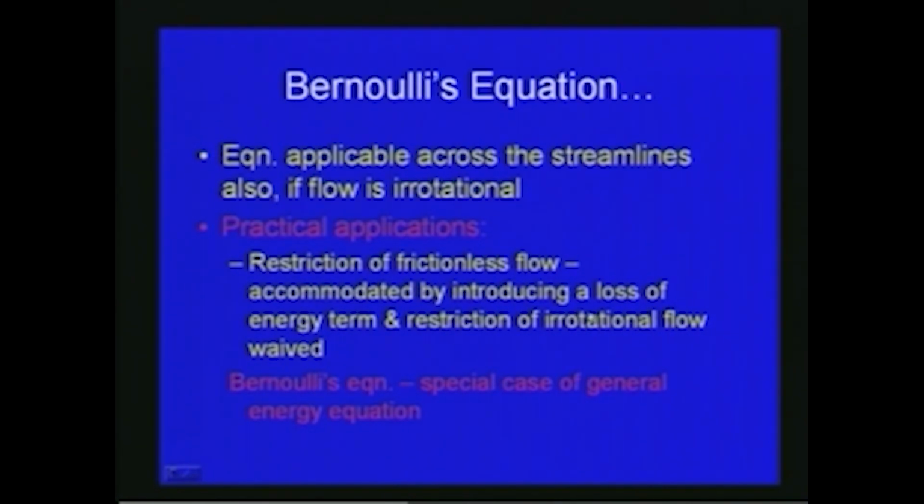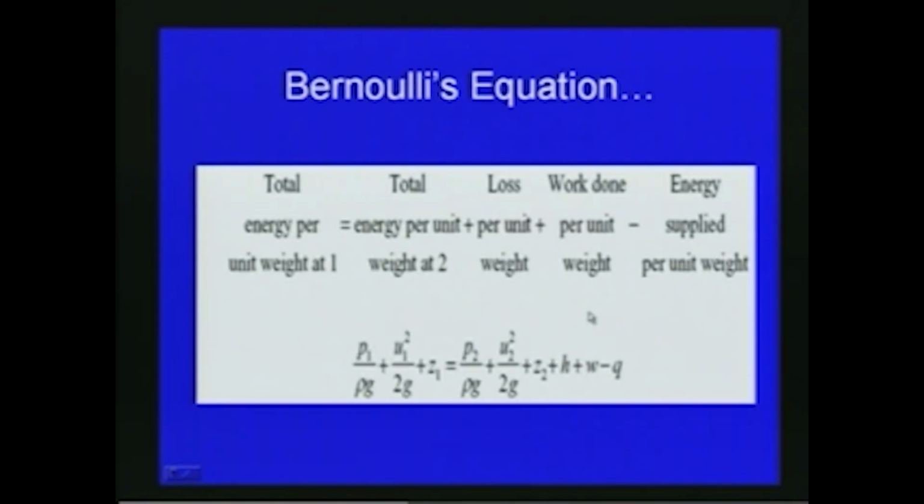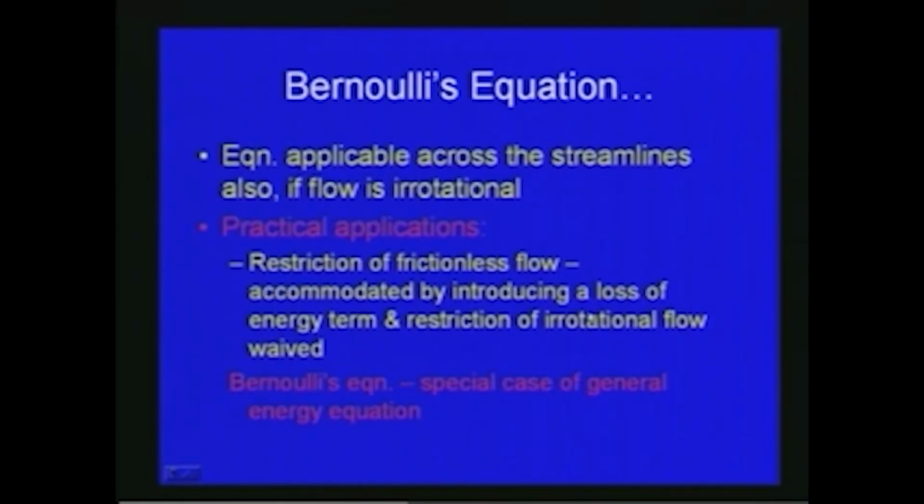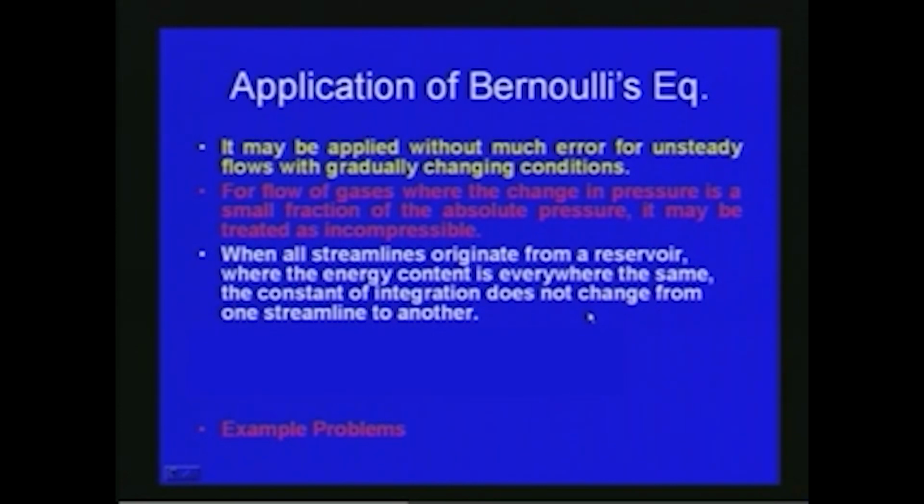So the general energy equation which we have seen here, Bernoulli's equation is a special case of it. Now with respect to this, we will be discussing some of the applications of Bernoulli's equation. Some of the things which we should always remember before using this Bernoulli's equation: it may be applied without much error for unsteady flow, also with gradually changing condition.